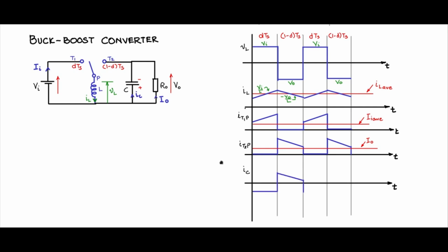So if I do that exercise, I will be bringing down, removing the average part, bringing down the waveform by I0. So this amount which it has come down is equal to I0. Now this current waveform will have zero average because the current through the capacitance has to be zero average under steady state conditions. So these are the various waveforms, the various voltages and currents that you will see in the buck boost converter.